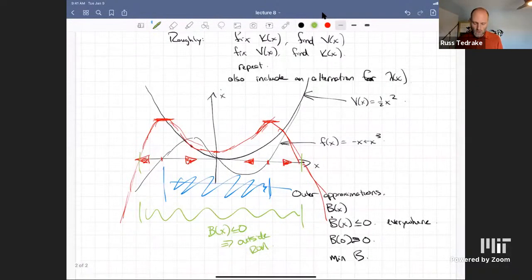It's as important to me that you appreciate the style of arguments that people are using. But in the case of just proving a region of attraction, you might not use this because it's potentially going to lie to you. Both of them have the property that they will converge to the true region of attraction if the degree goes high enough and the monomials and the degree of your multipliers go high enough. This one will be outside always. The ones we've done so far will be inside always.